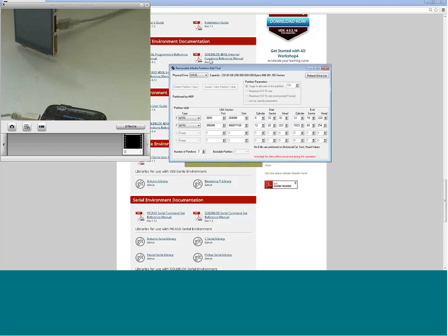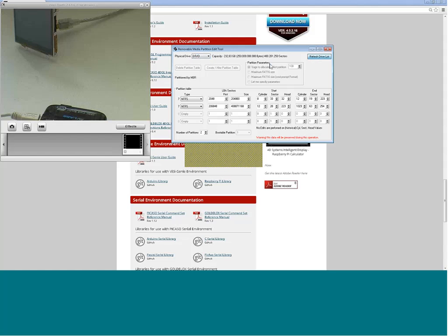It will come up. Press refresh. Then it will come up here as an SD card, and you can see FAT16 at the moment, and non-FS. You can see no file system, so raw is the rest of it. This is how I handle the SD card right now.